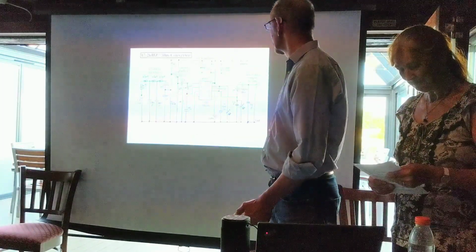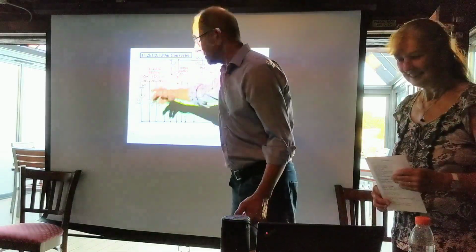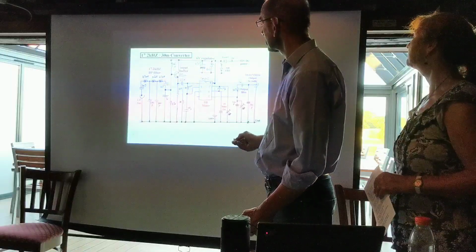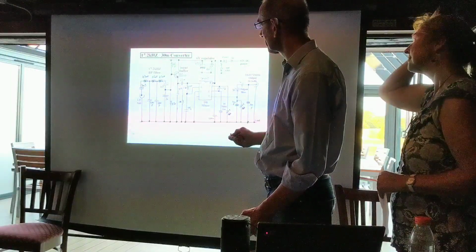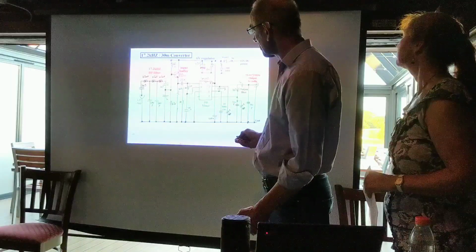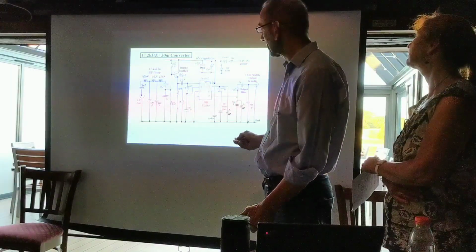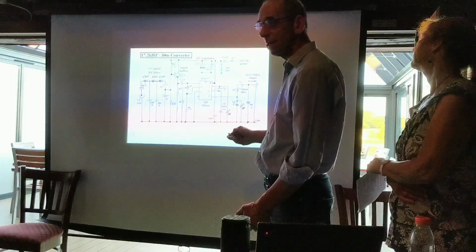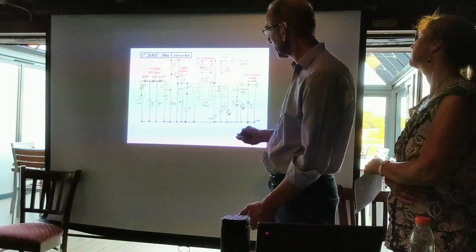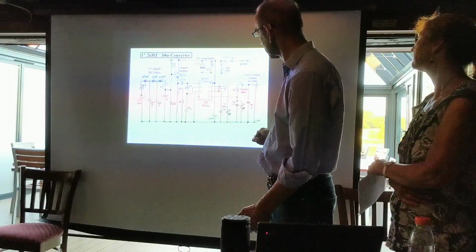And for those of you who are really into such things, there's a circuit. It's got all the usual bits. It's got a front end filter that gets rid of everything apart from 17.2 kilohertz. Now, these filters work best when they're lightly loaded. If you put a 50 ohm load across that, it tends to blunt the filter. So I put a little transistor in there just to keep the impedance nice and high at the front end, and a nice low impedance going into the mixer.